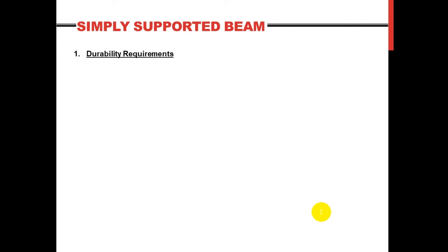Alright, let's talk about durability in a bit more detail. Corrosion of rebars can take action immediately once the passive state of the rebar is destroyed. Now, what does the passive state mean? Simply, the passive state is the state where the embedded rebar gains a layer of protection due to the surrounding alkaline nature of concrete.